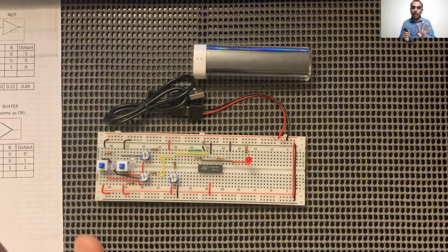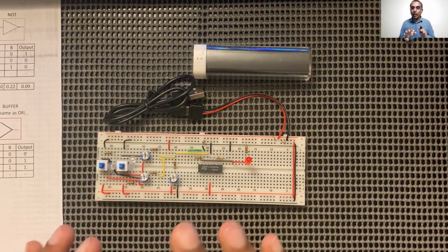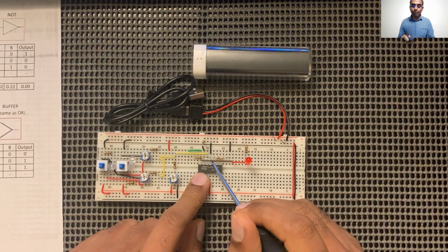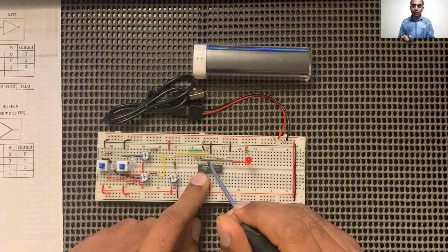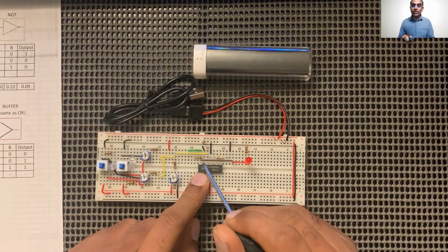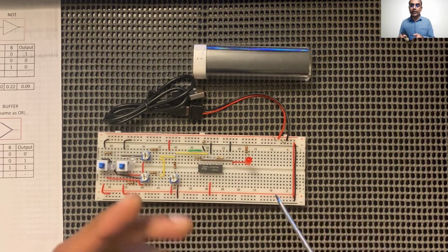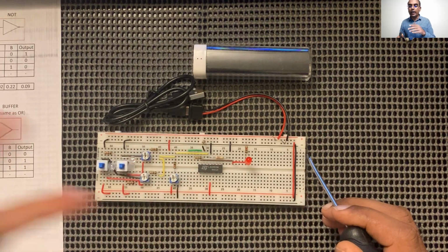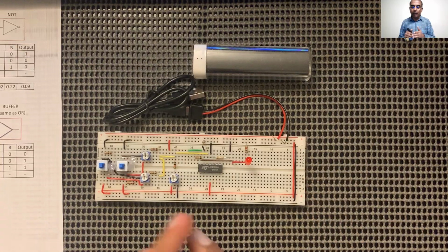It has 4 operational amplifiers within this integrated circuit chip. I will attach the data sheet of this amplifier to this video, and you will be able to see 4 individual op amps within this IC. We've used just one of them, and we've used pins 12, 13, and 14. Pin 12 is the input from the summation node to the operational amplifier, and pin 14 is the output to the LED. The LED is the one that will represent the output. If the LED is on, it means that this perceptron is firing. When the LED is off, the perceptron is not firing.